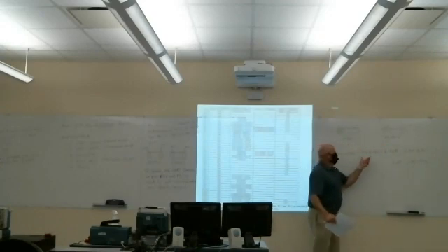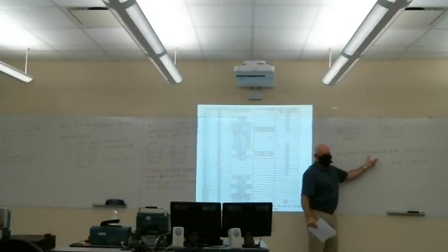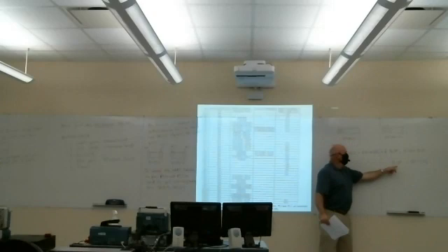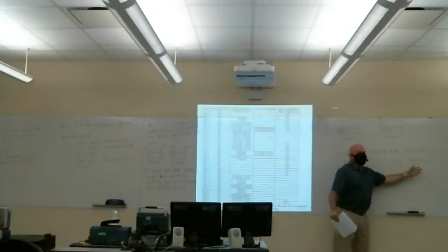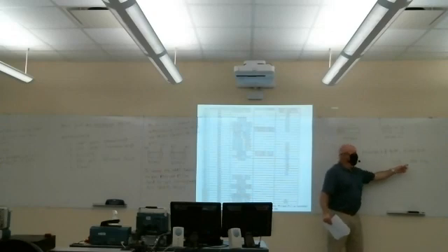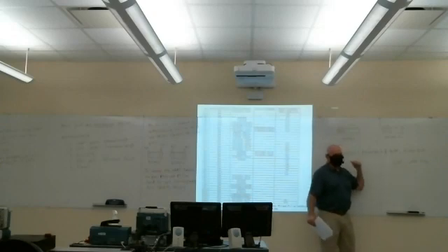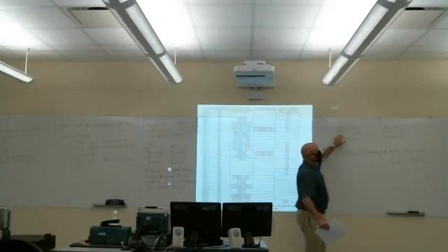So what does this do? This reads the current value that's in that P9 selection 1 register and ANDs it with 3F, which means if we AND with 1, it doesn't change the contents. But if we AND with 0, it will clear those respective bits. So what is this going to do? It's going to set those 2 bits in that register, regardless of what they currently are.